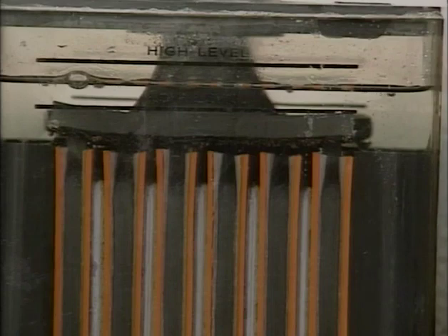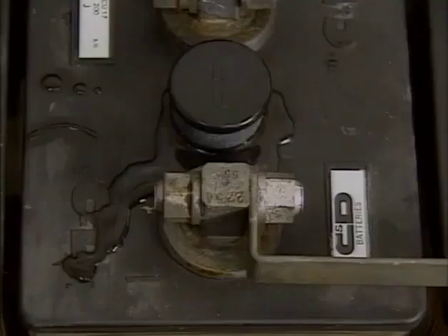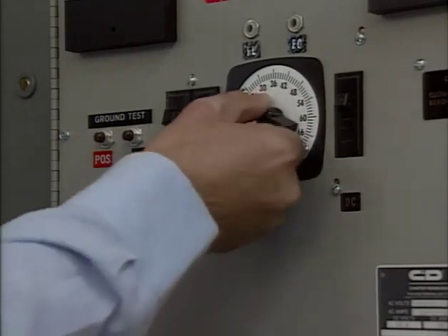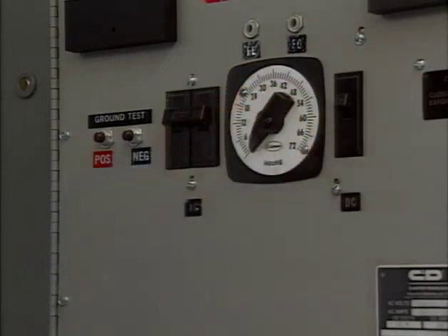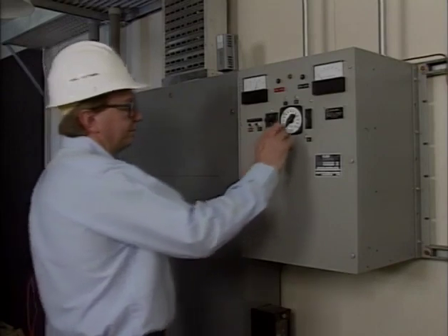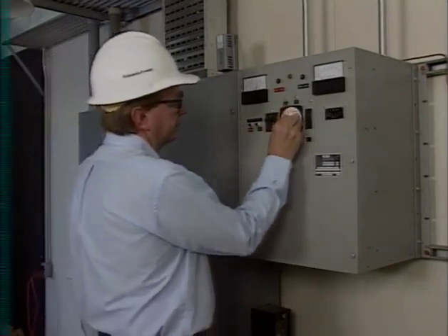The cells are also watched for excessive or violent gassing, which can distort the plates, create a high level of explosive gases, or cause the electrolyte to overflow. The gassing shown here is normal. If the temperature approaches or exceeds the limit, or if overflowing or excessive gassing is observed, the freshening charge should be stopped immediately by turning the float equalize timer or switch back to the float position. The battery is left on float until the cells cool down to 100 degrees Fahrenheit or 38 degrees Celsius. Once the cells have cooled, the freshening charge can be resumed.